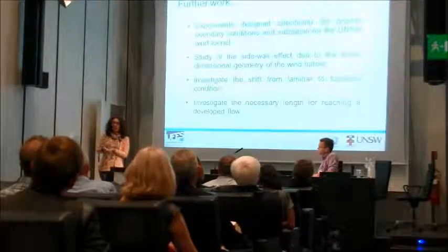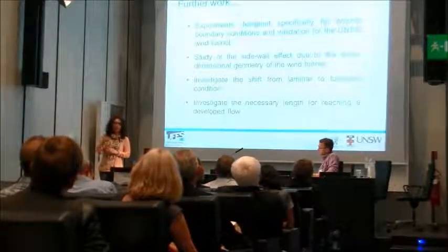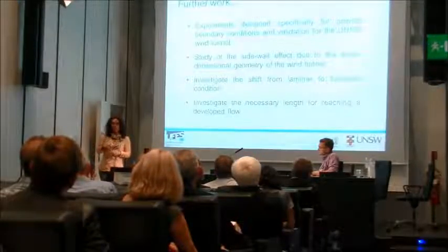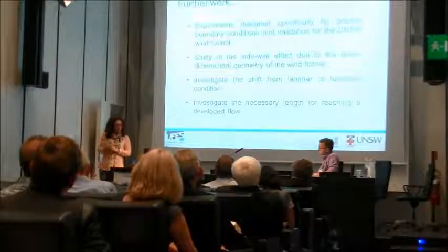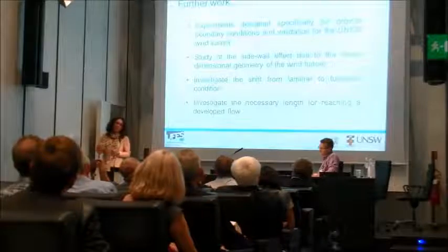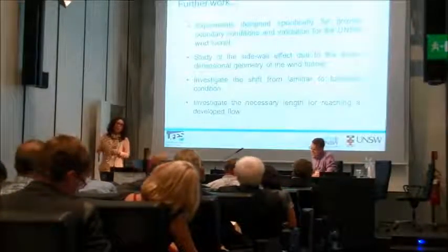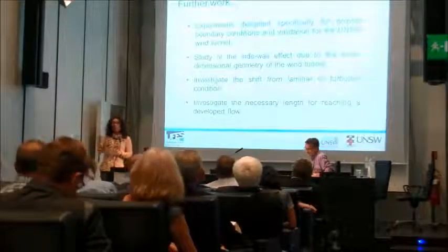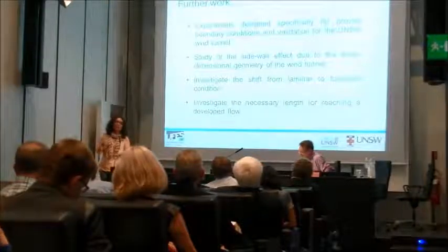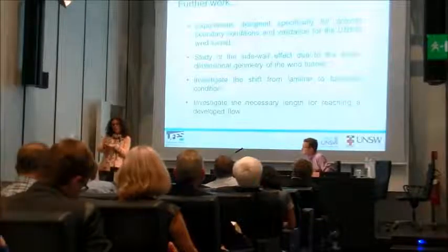flow inside. So I guess the next right thing to do is to do it in 3 dimensions, because with the computer power we have today, it's pretty easy to do a 3-dimensional simulation. We have to shift from laminar to turbulent if we want to keep the wind velocity inside the tunnel. But actually, the most important parameter is not the speed, it is the friction velocity on the liquid surface. That's what we have to bear in mind.